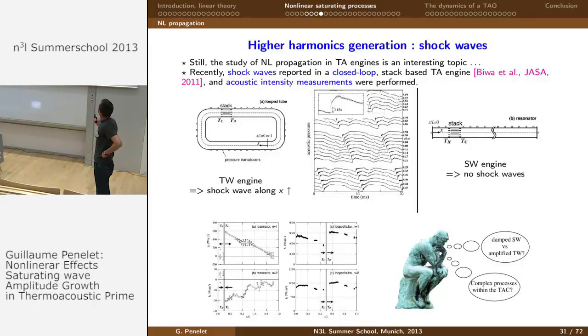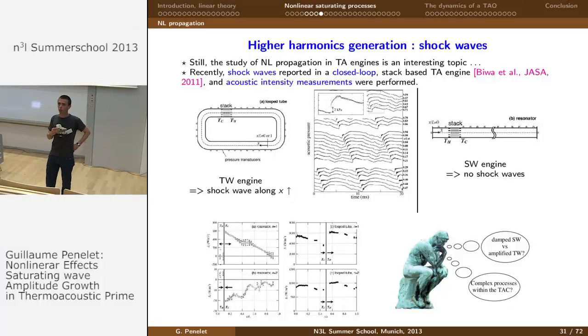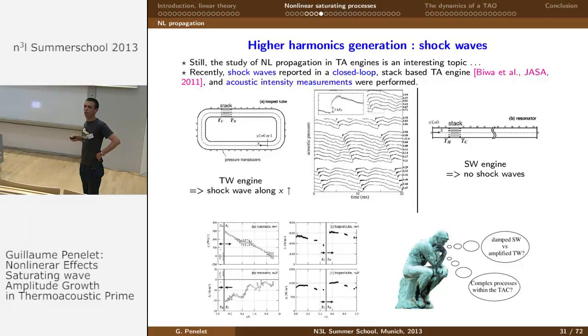And so Dr. Biwa has shown by the measurement of acoustic intensity that in the case of a closed loop, not only the fundamental but also the first harmonics are amplified through the stack, while in the case of a standing wave engine, the higher harmonics are damped through the stack. So this may be the reason why we can observe a shock wave in this configuration, but not in that configuration.